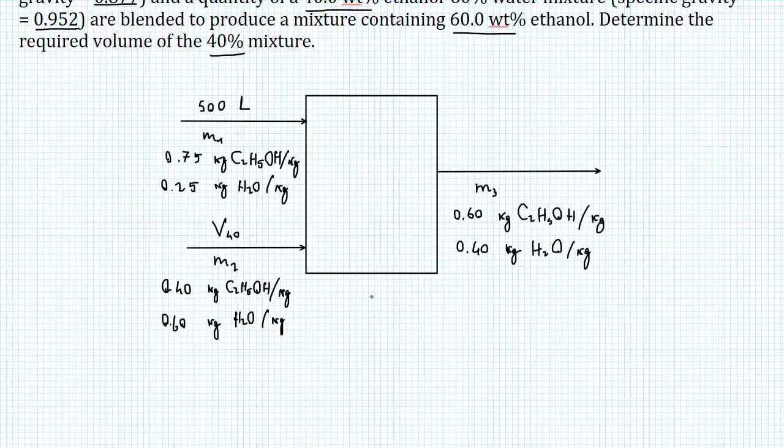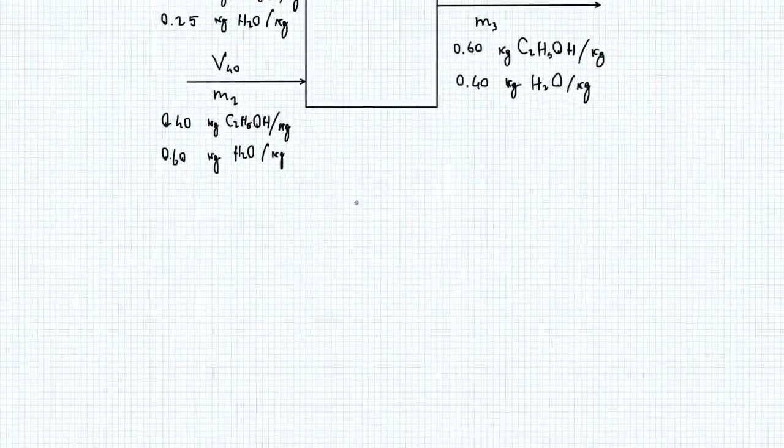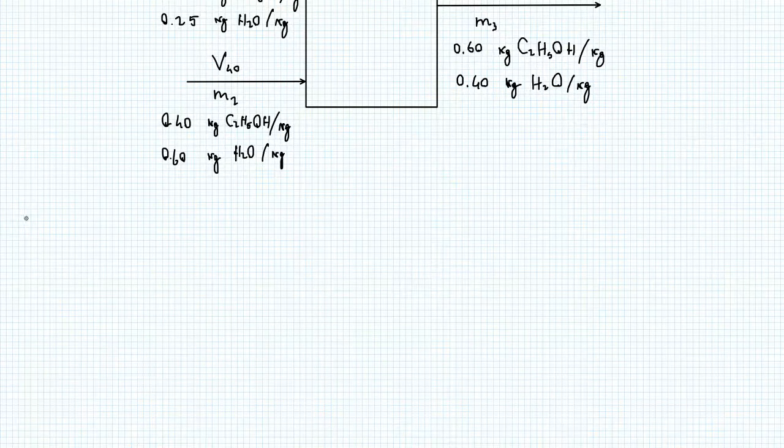Now, before rushing into the calculation part of the problem, it's important to perform a degrees of freedom analysis. Now, what this is, is a subtraction. So we look at the number of unknowns that we have, and we subtract from it the number of independent equations that we can set up. So let's look at how this actually works. We write unknowns minus independent equations, and there can be three possible results. It can be equal to 0, more than 0, or less than 0.